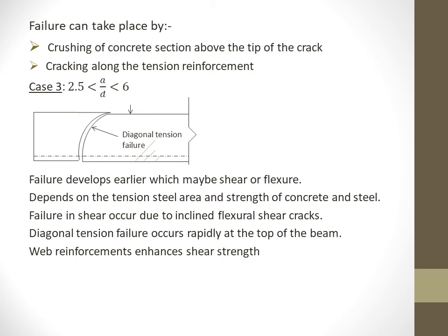That means we have to add more reinforcement so as to increase the shear strength gradually, and it can be carried until failure occurs in a shear tension mode, that is yielding of the shear reinforcement, or in a shear compression mode or in flexural mode.